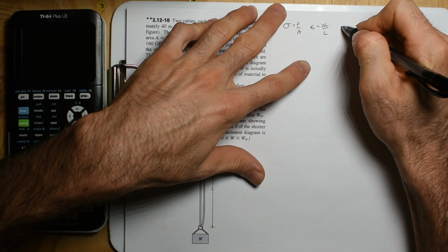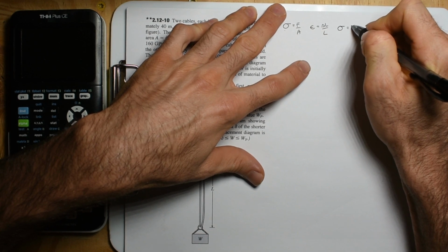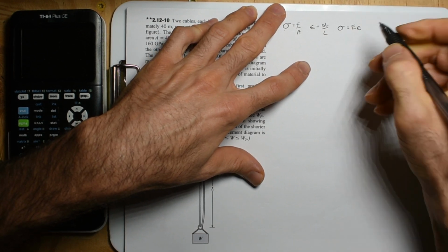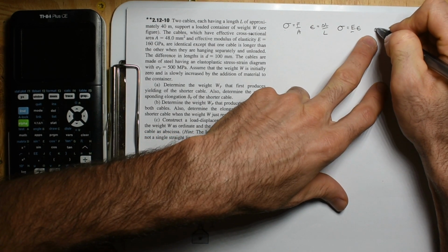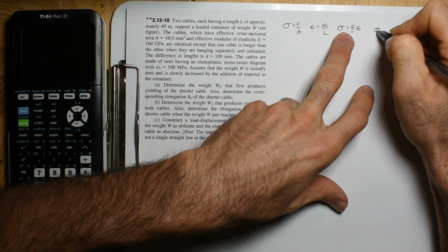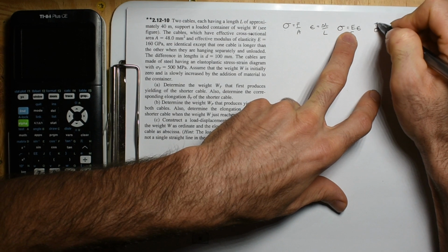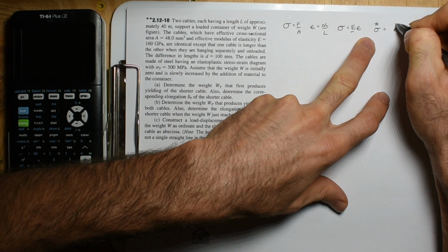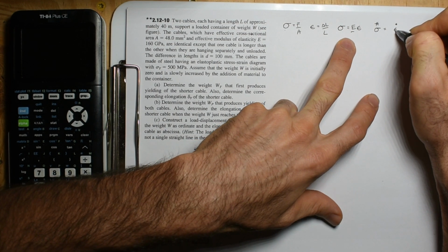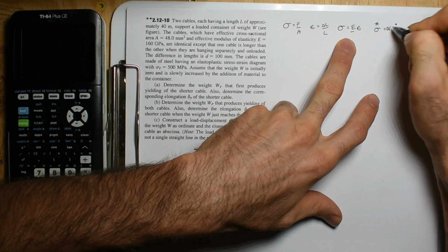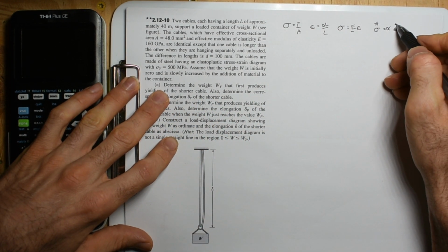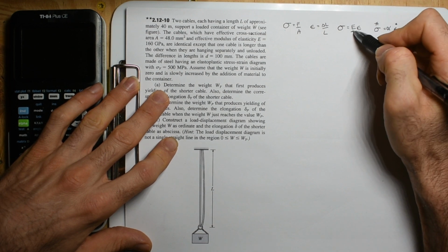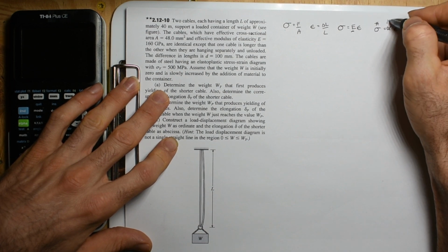And then we have what relates them. It's strength is E times stretch. Put the E's however you want. But this is the constant. This is the modulus of elasticity. It relates the two because it says this normal number is equal to this tiny number of strain, or change in length, by some sort of proportionality constant. And to get a tiny number to equal a normal number, this E has to be fairly big.